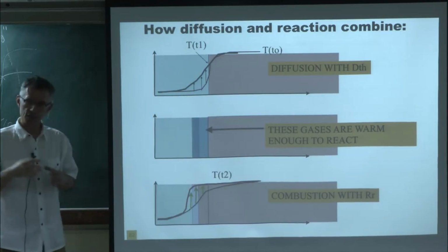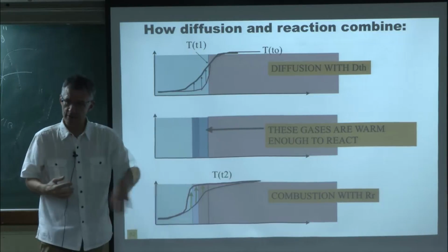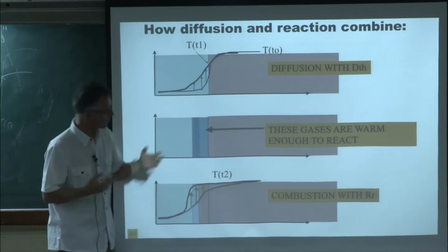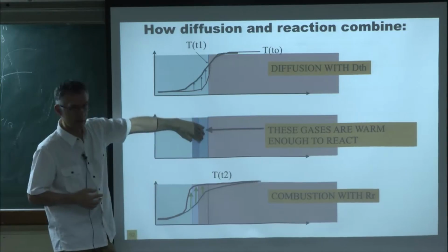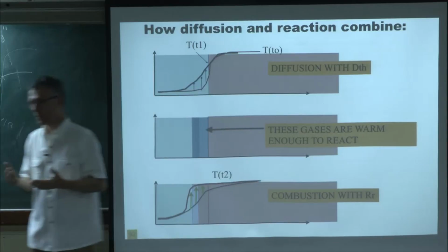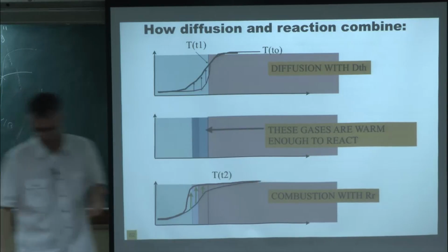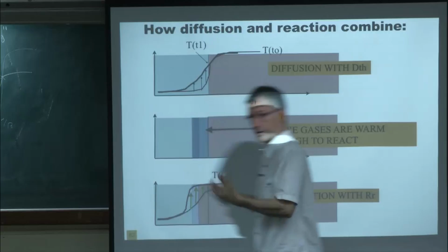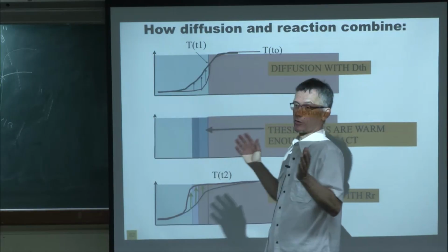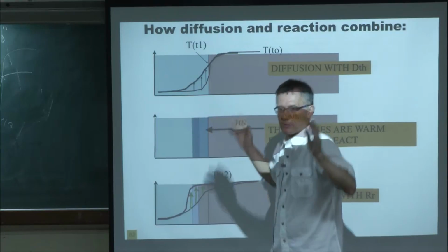You see that this propagation of the flame is essentially a two-step mechanism. You need first to diffuse the heat, and then you need to react it. The other way to say the same thing is that if the flame is here, and I am a premixed element, it's a strange life which I have, because I'm cold. I feel, hey, nothing can happen to me, I'm cold. I cannot burn.